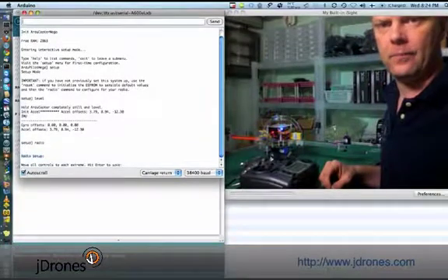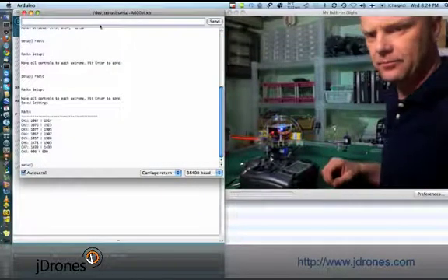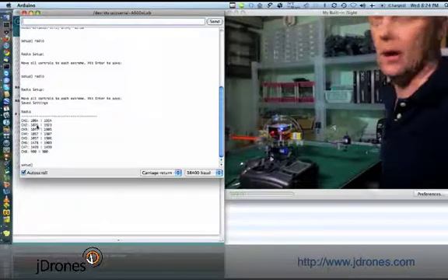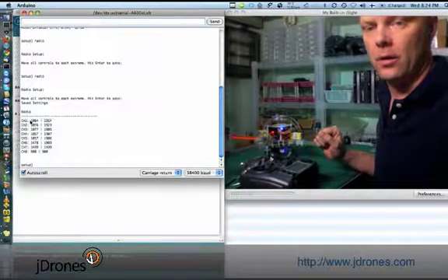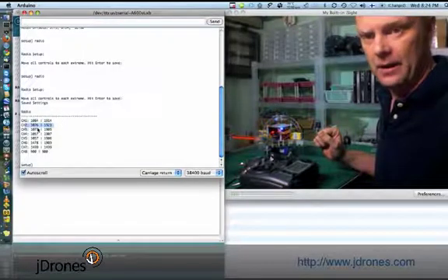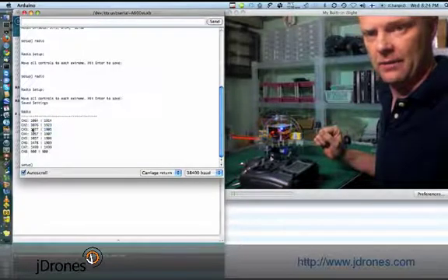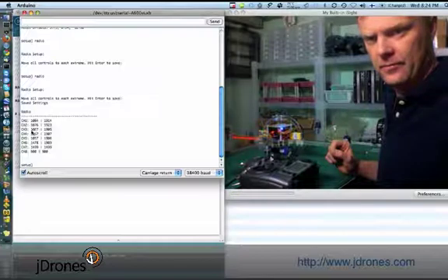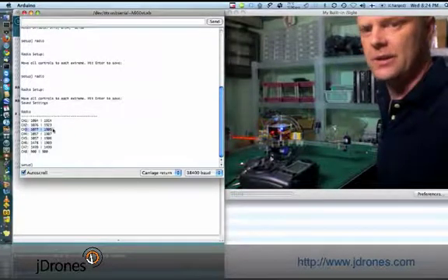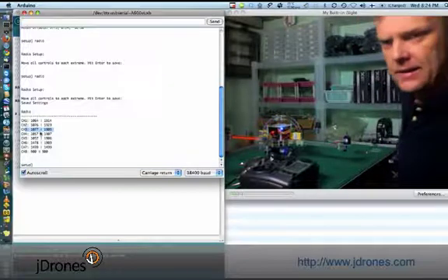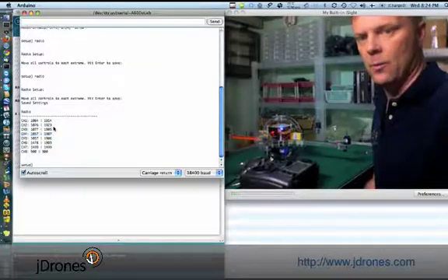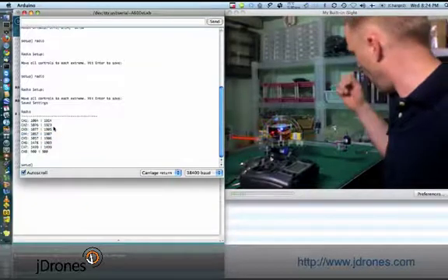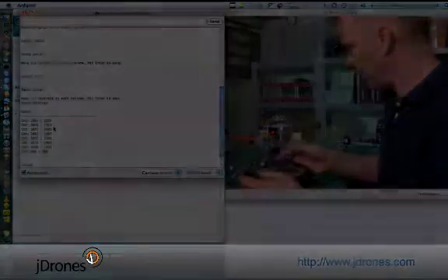Now, there. And we can easily see that ArduCopter Mega also received all those channel PWM pulses, because they look different in the channel view. Just like channel 3, which is the throttle, it says that my minimum throttle is 1077 and the maximum is 1905. Okay, good.